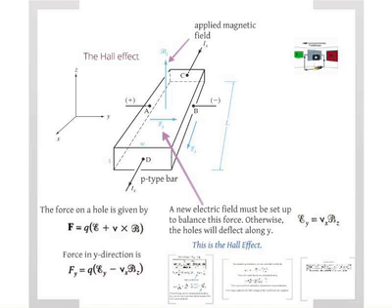And the reason we are studying this today is because this turns out to be the characterization tool to understand and study semiconductors. So before we dive into the physics, let's make sure we understand very clearly why we are studying this. Okay? Hall effect is useful to measure the carrier concentrations in any material. So let's say someone gives you a bar of silicon and asks you, okay, tell me what the carrier concentration is. Hall effect allows you to do a very simple measurement to very accurately estimate what the carrier concentration is. So it's an extremely useful tool, as you can imagine.